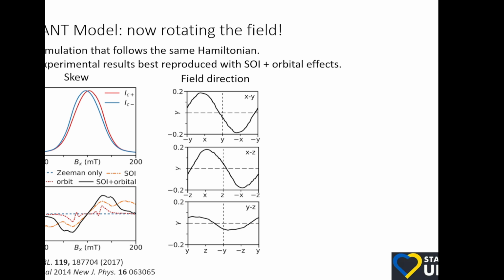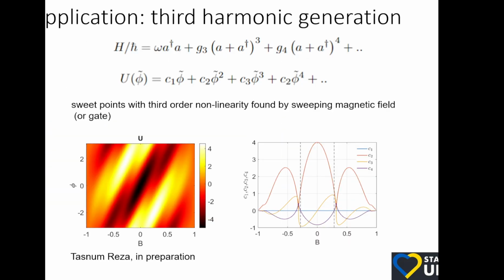It's not completely direct, like the current-phase relation measurement would be better. But for instance, complementary to this, if we can measure in the microwave the third harmonic effect, the third order term, that you realize with a SNAIL, that would be sort of another proof.